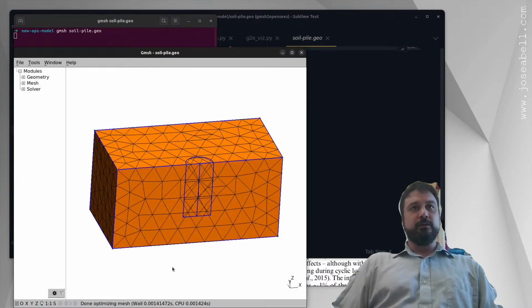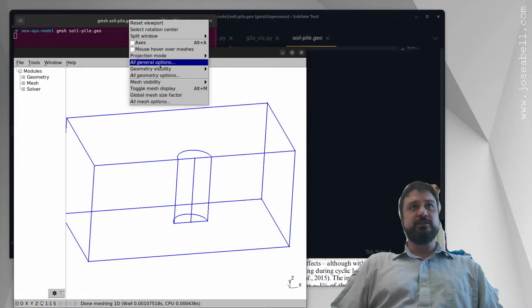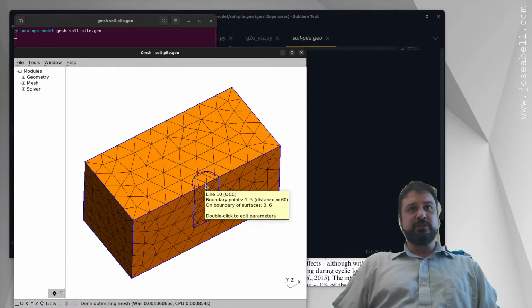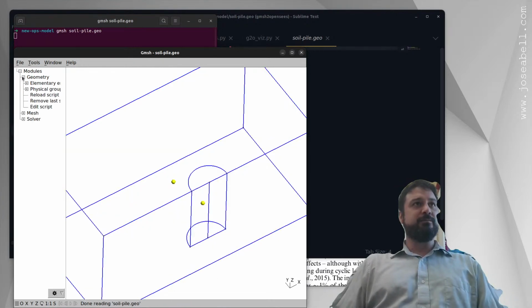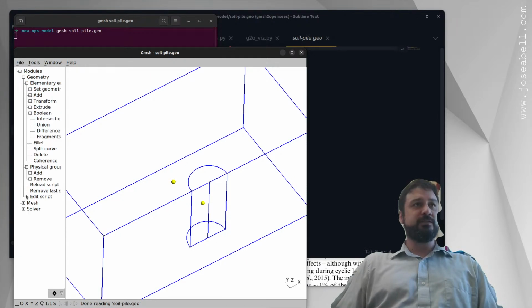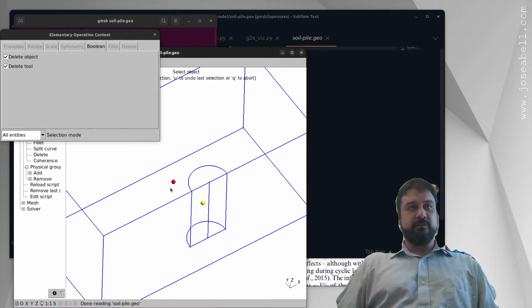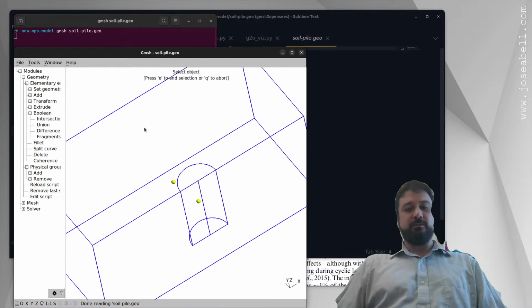Here we go. So these are two, I guess, independent volumes. If I take a look at the volumes, let's see, geometry, visibility, volumes. Yeah, those are two independent volumes. So the meshes don't mesh together actually. So to get them to mesh together, we will apply some things over here. So Boolean, let's say, was it the fragments tool? So let's go this E, select this, fragments. If I do that, I think it merges the model, maybe not.